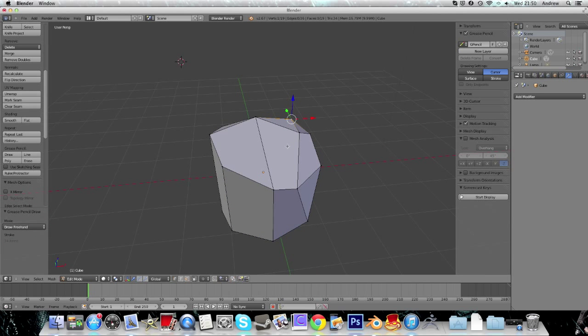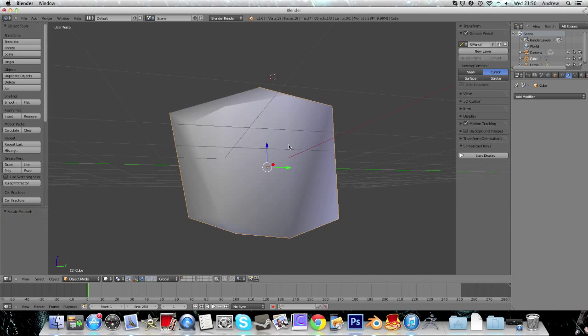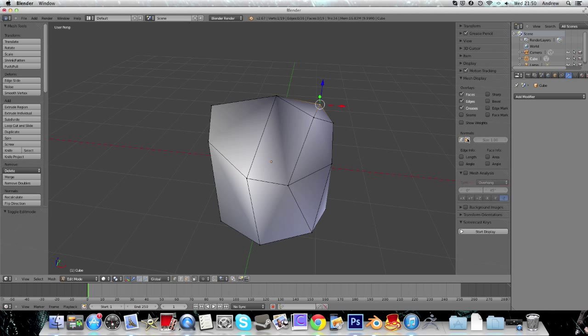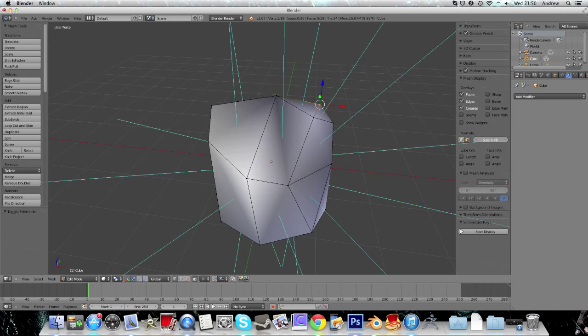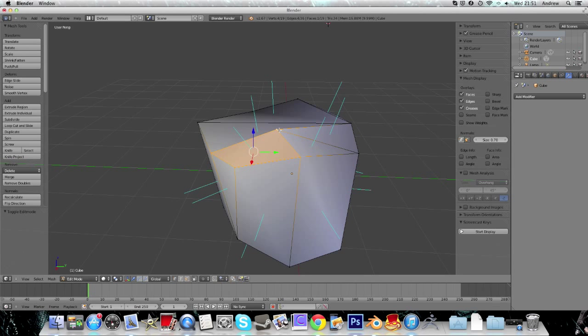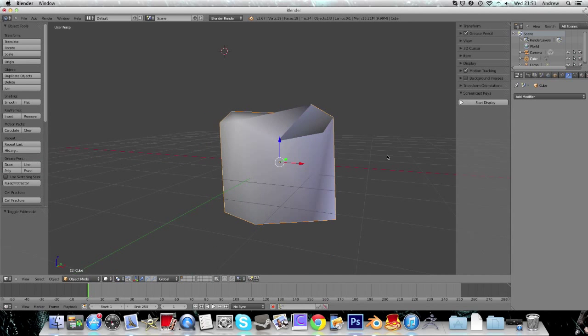And I also want to mention the normals. That's the final thing that I'm going to mention. It's also important when you're modelling, and it goes back to smooth shading, because I've got smooth shading on right now. When I go into edit mode and turn on the normals in the mesh display, normals display face normals, and then change the scale of them depending on your scene. If I flip one of these by pressing space and flip normals, then we can see it's gone kind of black here. You've probably seen this before, and you might not even know what it is. It's because the normal is facing the wrong way, and it affects the smooth shading, it affects glass effects, it also affects textures, and probably quite a few more things.